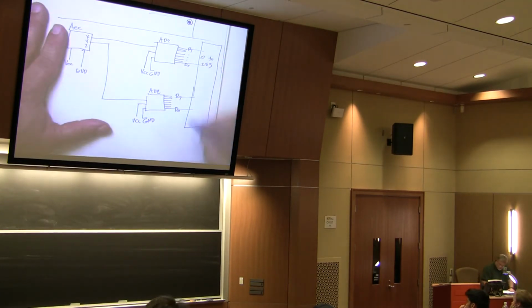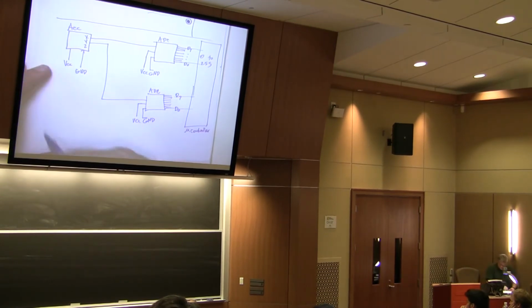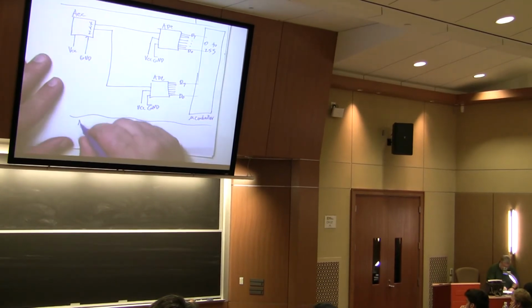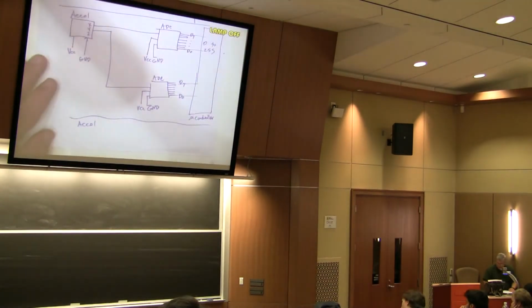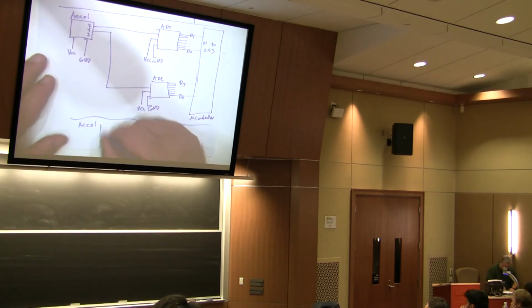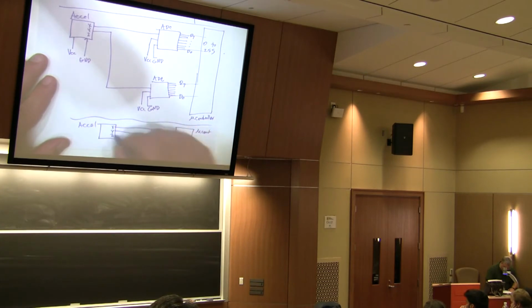Some port, whatever the port is. Now, here's the thing that makes life a lot easier. Instead, we're going to have our accelerometer, and we're going to have the X, the Y, and the Z go into our ports, maybe we call it AN0, AN1, and AN2. Of course, this has VCC and ground as well.